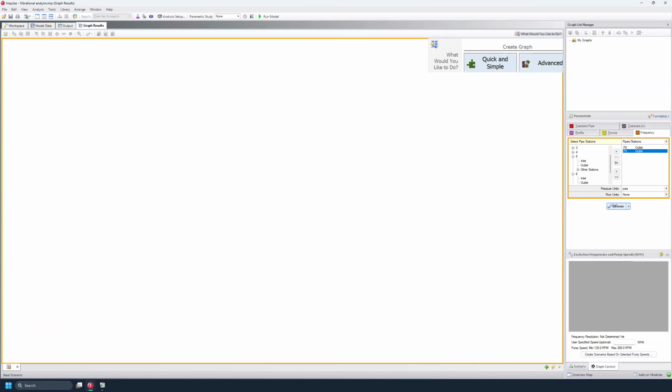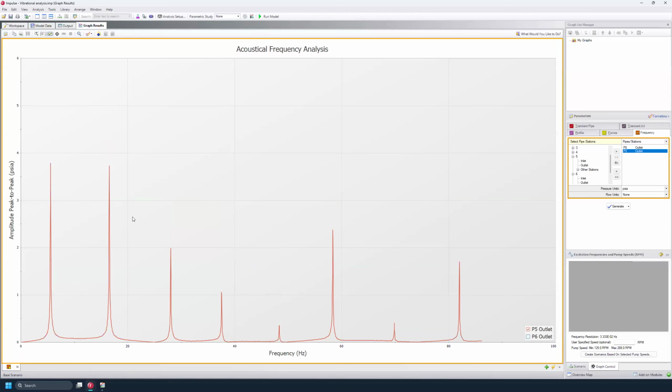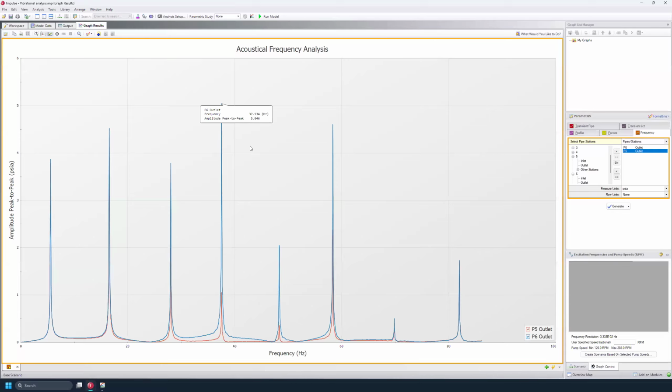Okay. All right. So we can see the more sensitive subsystem here in blue and the T in red. So the lower frequencies are exciting the T more, and the higher frequencies are more severe for this subsystem. And the higher frequencies have more potential for damage. So let's take the 2 higher frequencies that have a large magnitude so we can drag highlight this.